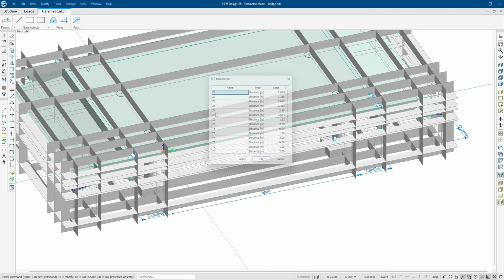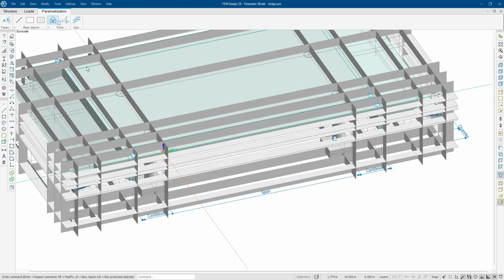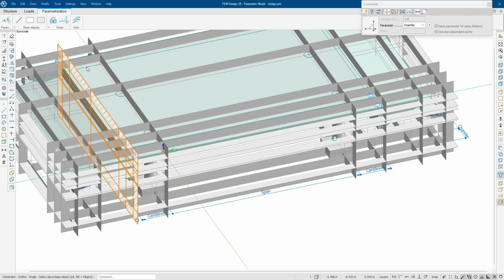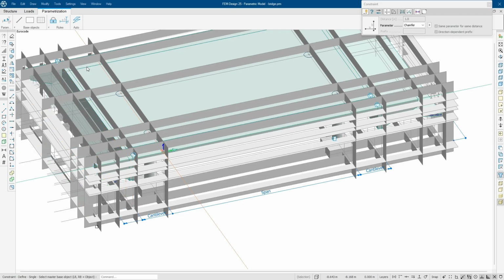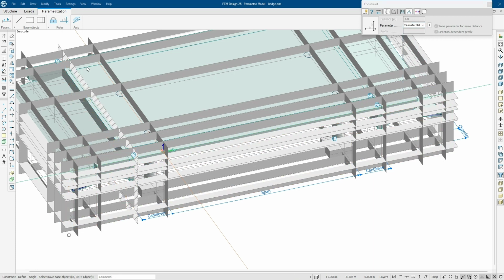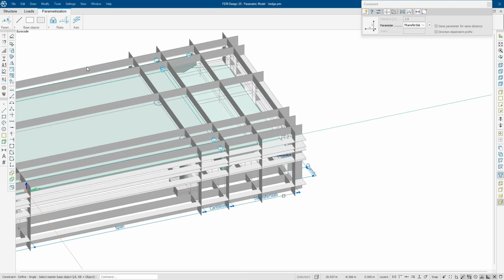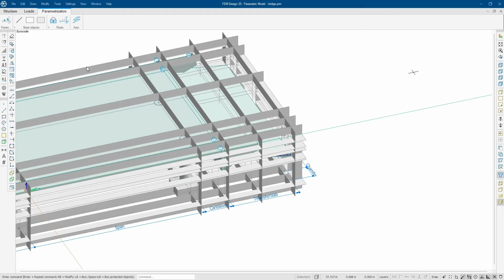The automation doesn't know how you place these constraints. So that's why it's sometimes better to define these constraints yourself, like the transfer slab length. Let's say that this is 6 meters, and we want to define it from this wall. So from this wall to this wall, and now it's what we want. Actually, we selected the wrong parameter. This is the transfer slab length. And now it's correct. So you can start with the automation and define these constraints yourself, like they're supposed to be.